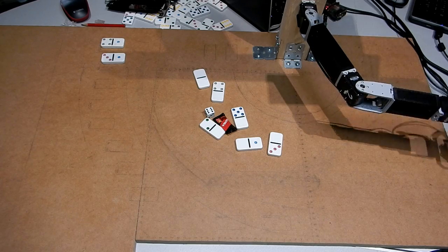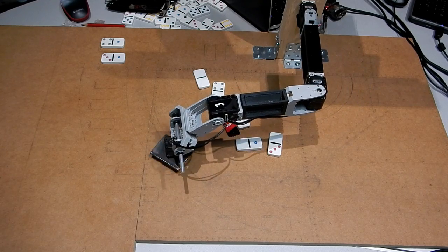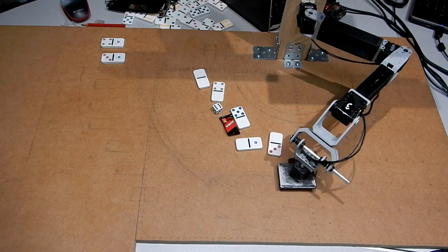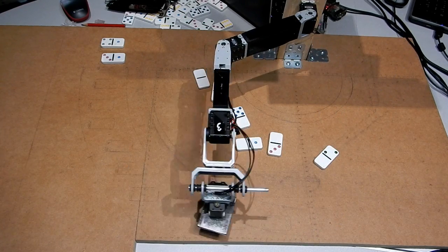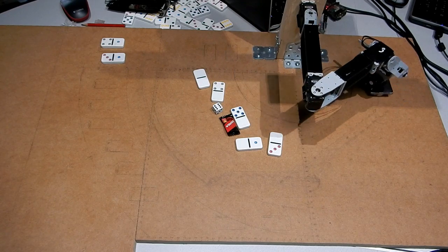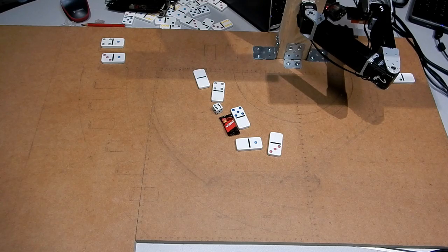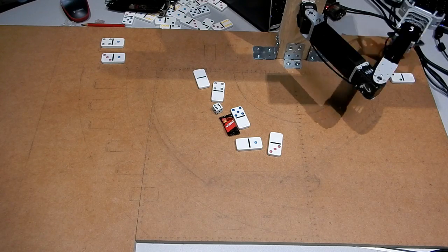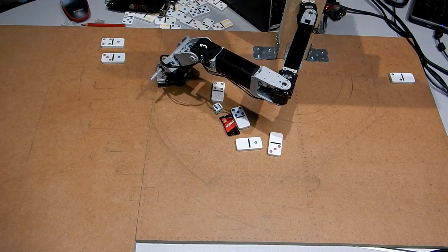The algorithm was based on three basic motion functions that made the end effector move in straight vertical, horizontal, and diagonal lines. Managing to do so was rather difficult, since the revolute joints do not easily generate linear motion. The approach taken was to discretize straight paths from one position to another, and then progressively follow it by going to each point of those paths.